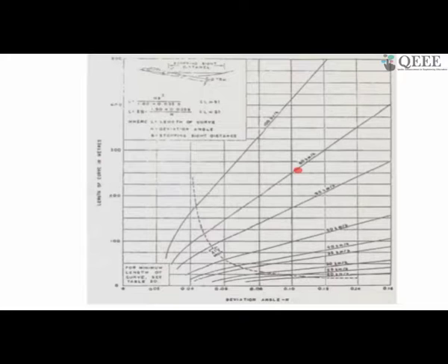So this becomes more critical than the summit curve, because in the summit curve, as the vehicle is going in the ascending gradient, naturally the speed is quite checked, and unless someone is pushing the accelerator too much, they are not going to overspeed easily. Here in the valley curve, without even pressing the accelerator, the vehicle can.